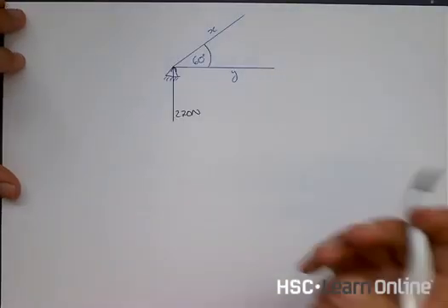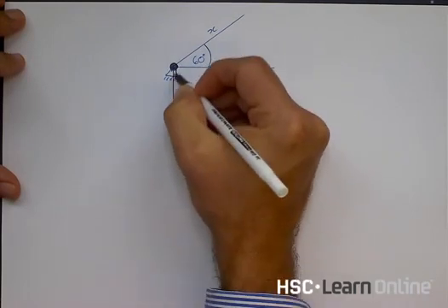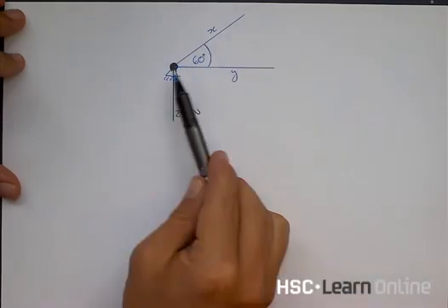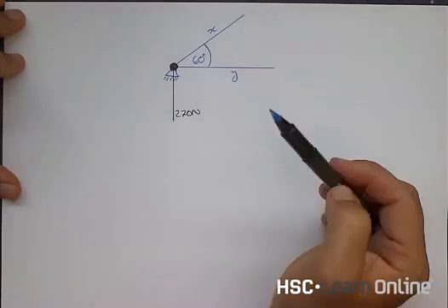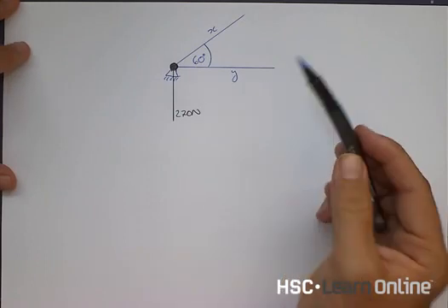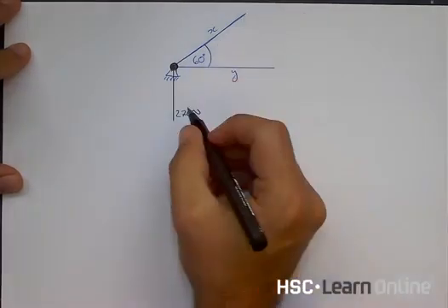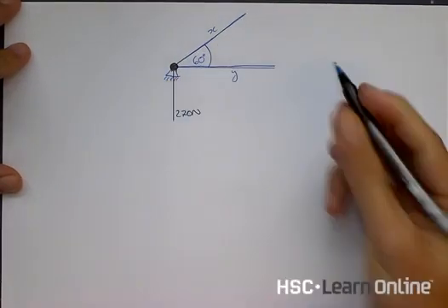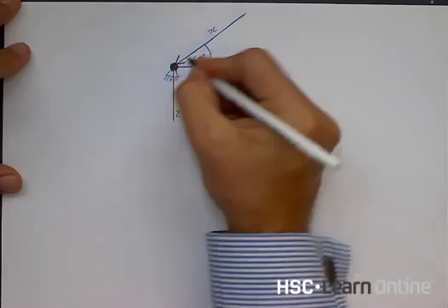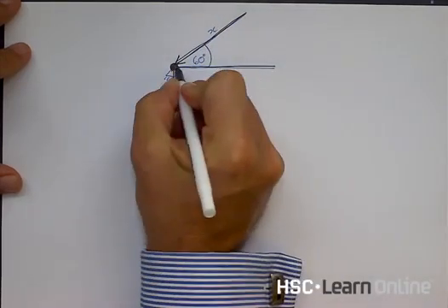And here it is. This is the joint that I'm talking about, and we're zoomed in. Here's my 270 newton force that came from my problem, and here's my member X and my member Y, and that's the angle of 60 degrees. And once you do that, the problem becomes quite a lot simpler, because we know there's a force acting along that member, and a force acting along this member. So I'm going to replace member X with a force, and member Y with a force.